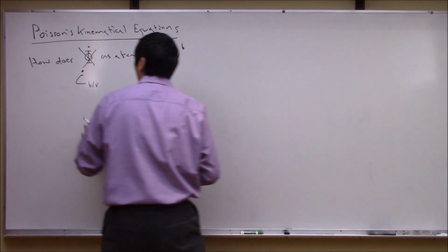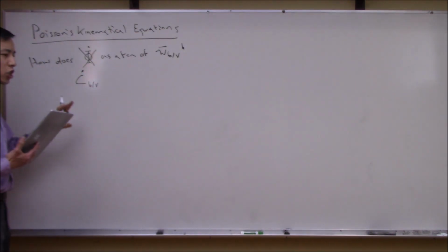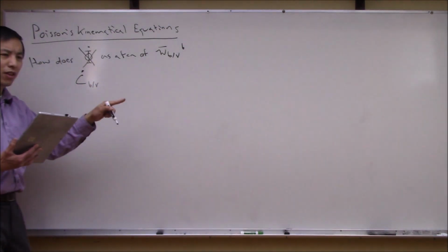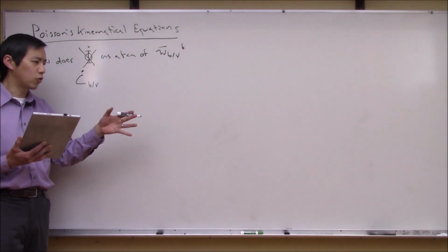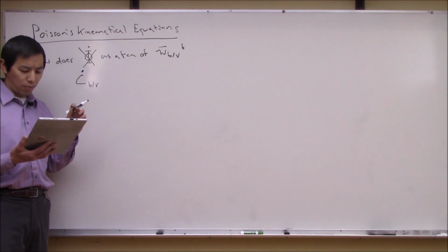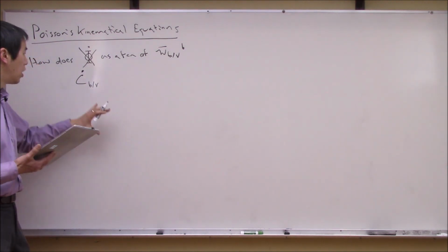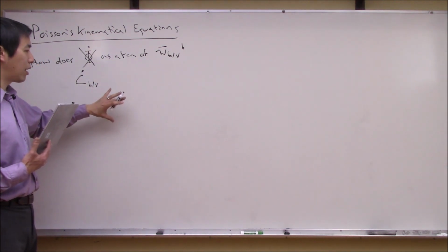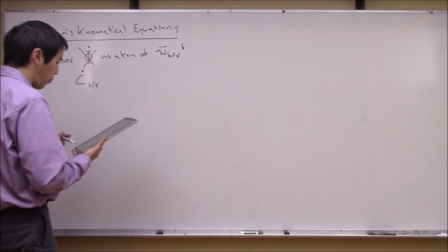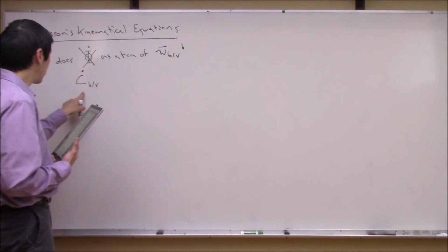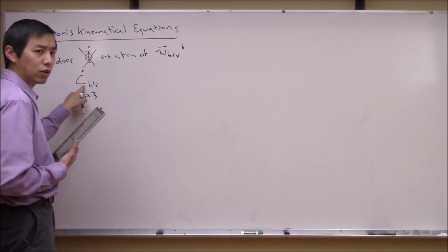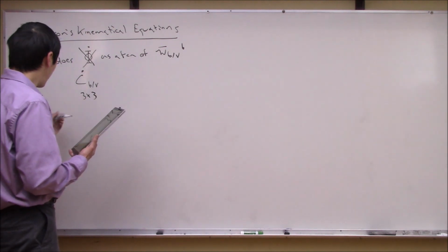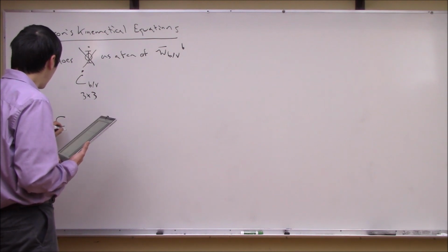Okay, so the derivation, I will leave that to Stevens and Lewis. The textbook by Stevens and Lewis, Aircraft Control and Simulation, 2nd edition, on page 28 has the derivation of this. But basically, it comes out to a very elegant form, where if you have the entire direction cosine matrix, remember, this is a 3 by 3 direction cosine matrix, we can write its time rate of change.